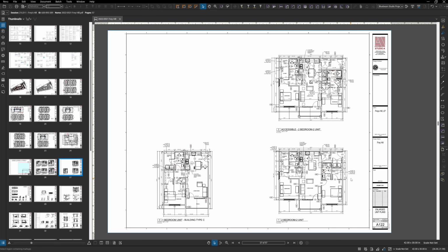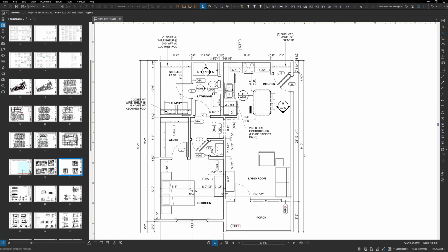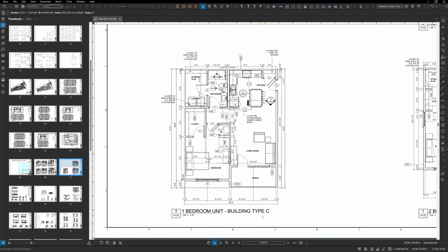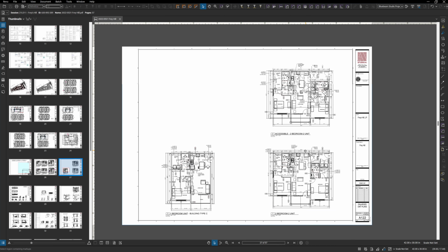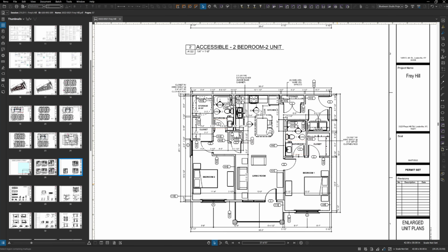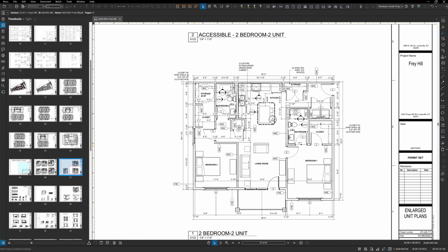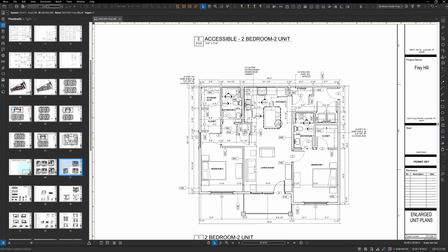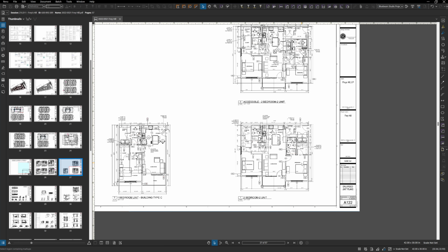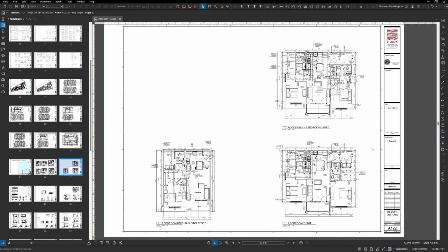If it's a market rate job, for example, LDG requires 50% step-in showers, so that's why we have 2 one-bedroom units that are the exact same unit in every way except for a step-in shower. Then we get 2-bedroom units on the ends of the buildings, and the only difference is they get a second window in this bedroom, which is just a nice to have.